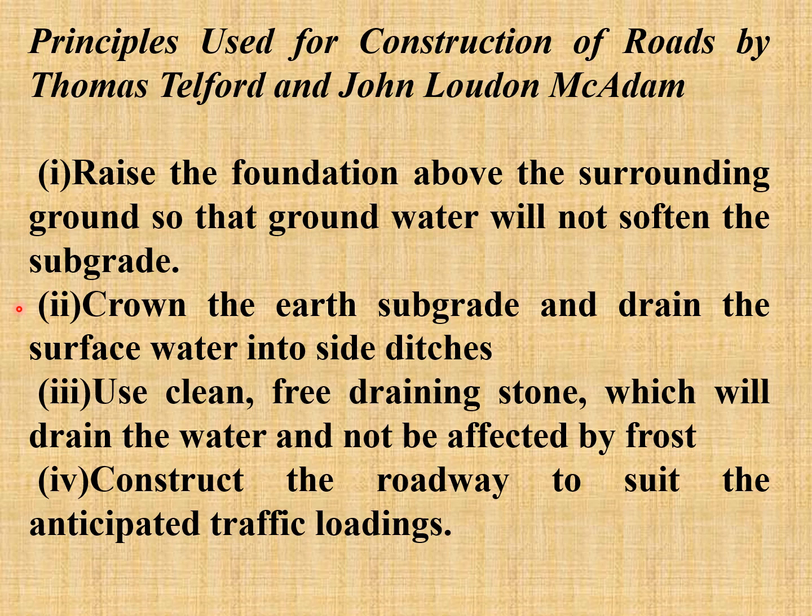Crown means just raise the mid part so that water can drain out laterally. Number three, use clean, free draining stone which will drain the water and not be affected by frost. Number four, construct the roadway to suit the anticipated traffic loading.